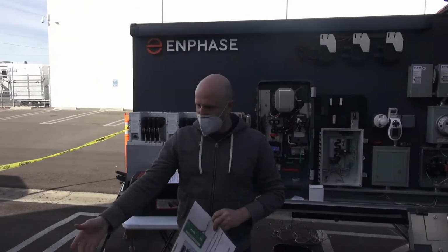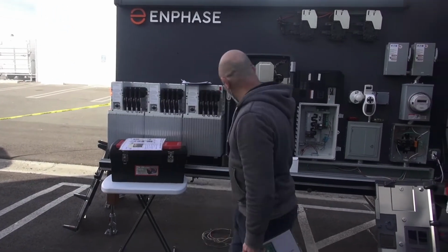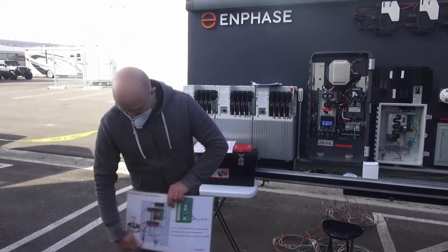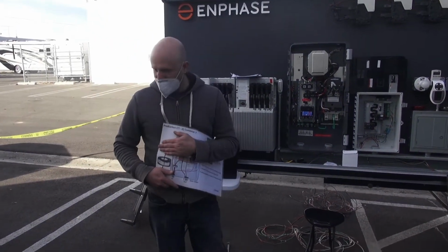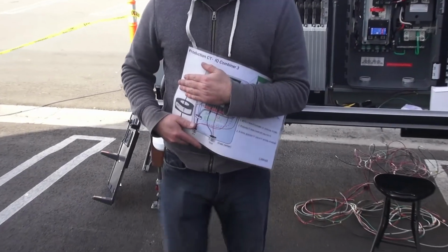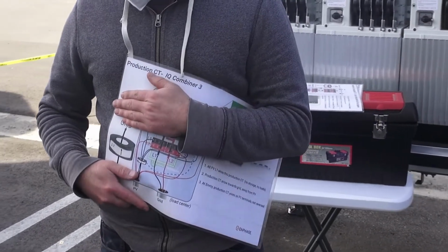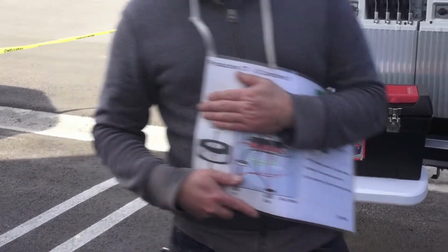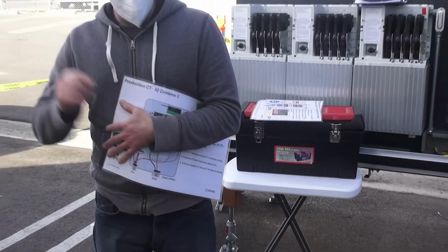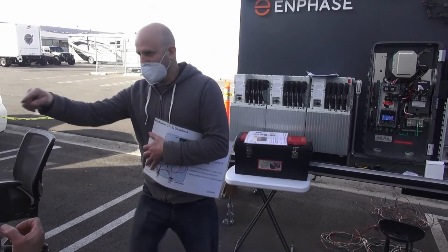L1. So only L1? Okay, so L1 goes through it. There's an arrow on that L1 CT. Which way does it go? And I'm going to make you be real specific. Does that arrow point towards the grid, away from the grid, towards solar, away from solar? So here's how I want you to answer me. The arrow points away from what? From solar.